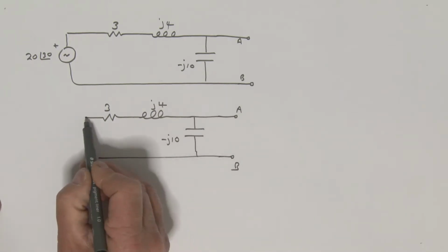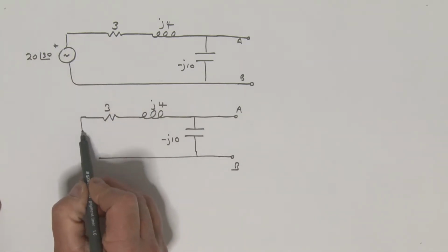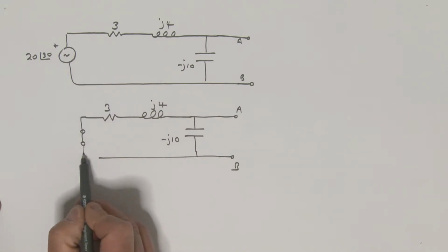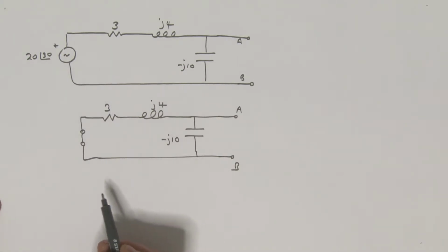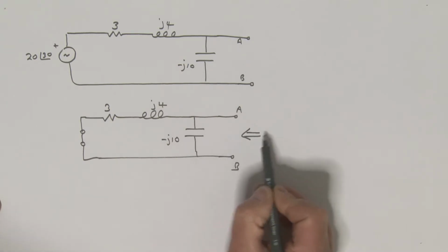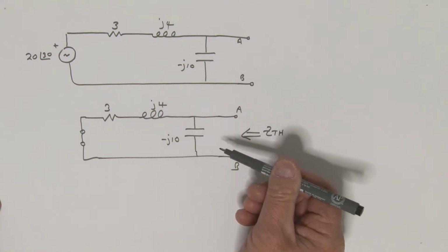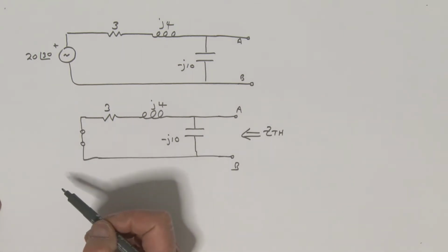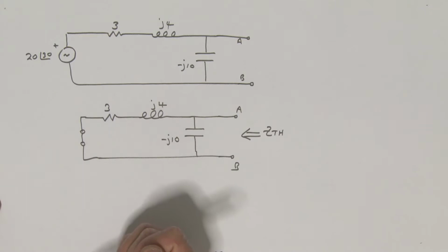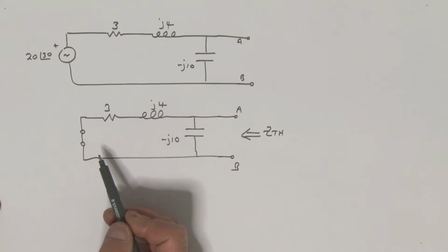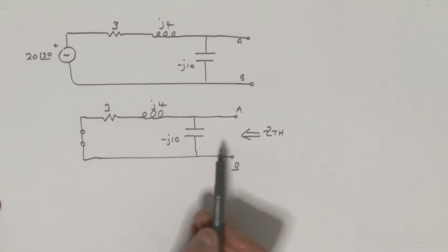And we're going to simply zero this guy over here. That is replacing it, since it's a voltage source, we're going to replace it with a short. So the Thevenin impedance then is the impedance looking in at these terminals, having zeroed all our independent sources. Now we can only do this really if we have a circuit that is made up of independent sources.